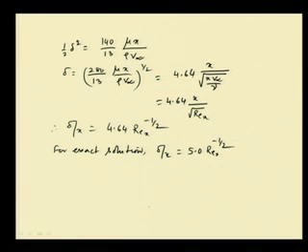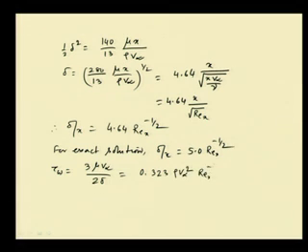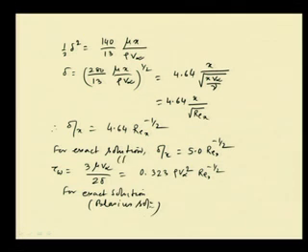And then in the boundary layer, we have some more things to be done for the hydrodynamic analysis, that is tau wall. Tau wall is equal to 3 into mu into V infinity by 2 delta, and this is equal to 0.323 rho V infinity square into Rex to the power minus half. Okay. And this we have already seen for the exact solution, which is the Blasius solution.